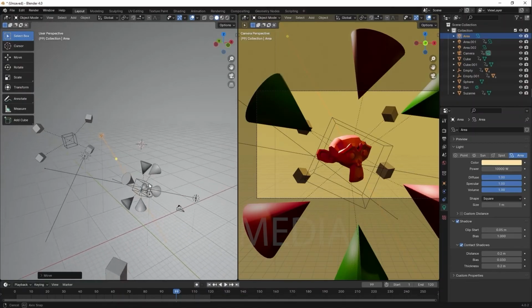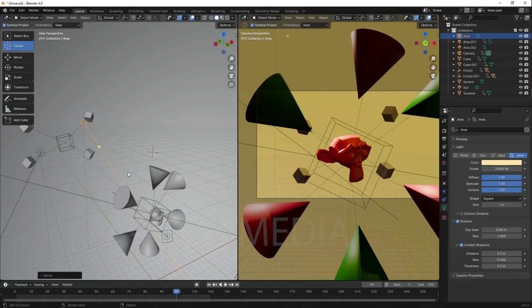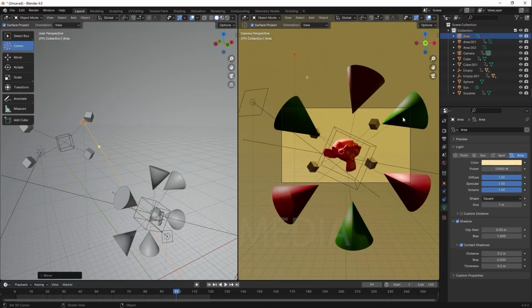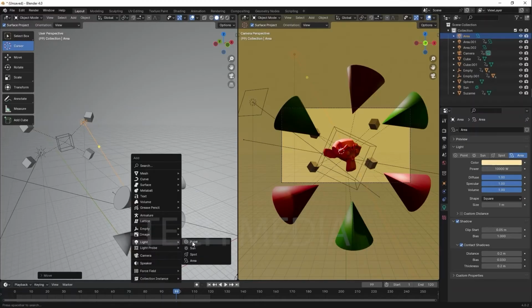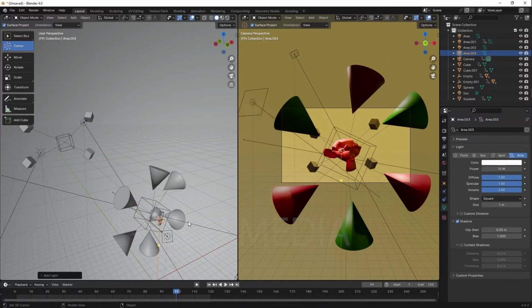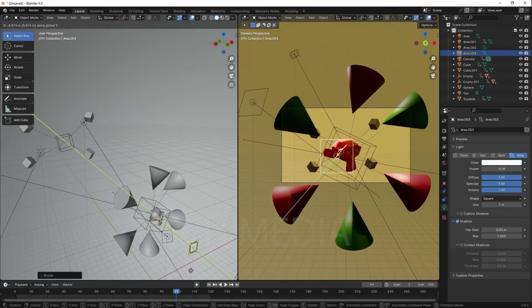All right. Okay, so we're gonna have one more light, this time directly in front, because you notice that these guys, they're a little bit too dark. So we need to fill some light there. Probably not very intense, right? Rotate on the x-axis 90 degrees, and G on the y-axis to bring it to the front.